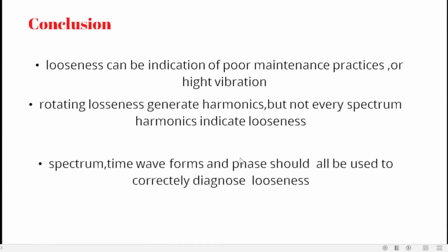So in conclusion, looseness can be an indication of poor maintenance practice or high vibration. Rotating looseness generates harmonics, but not every spectrum harmonic indicates looseness. Yes, this point is very important. We must check the phase to see if we have looseness or imbalance or other things the same. We can measure in FFT and measure the phase every time. Spectrum, time waveform, and phase should be used to correctly diagnose looseness.